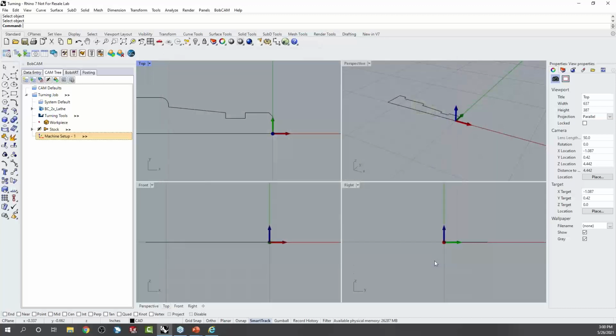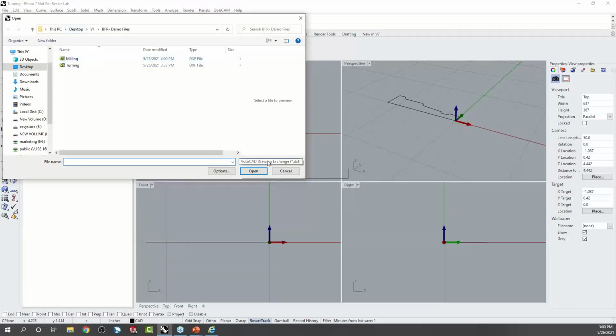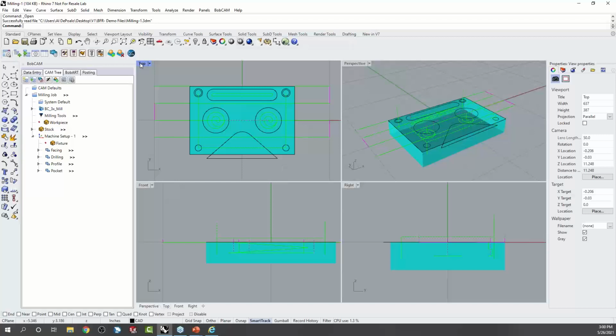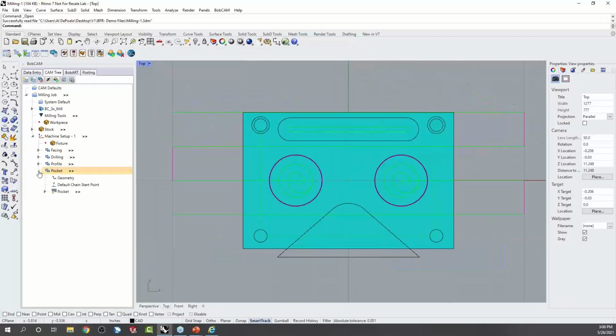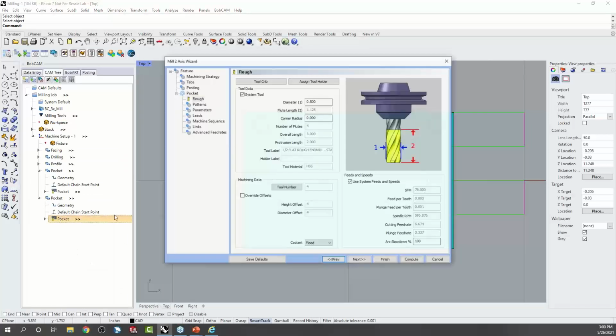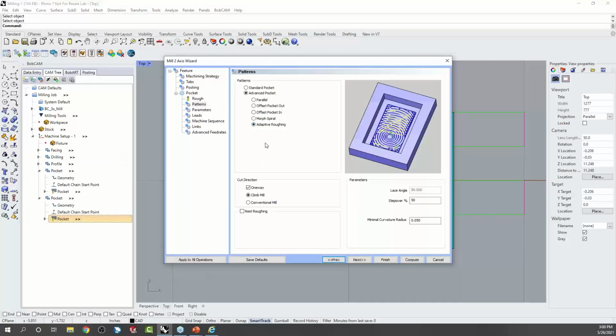And can you show an example of your adaptive toolpaths? Great, yeah. So we have 2 through 5 axis adaptive toolpaths. So if we go back to, let's see here. Okay. So if we look at this section here, this is what I'll use for the adaptive. Again, I'm going to copy this feature and then paste it so I can use all the same settings. I'll select the boundary that I want to work with, which is right here. I can edit the operation pattern and I'll go to adaptive.